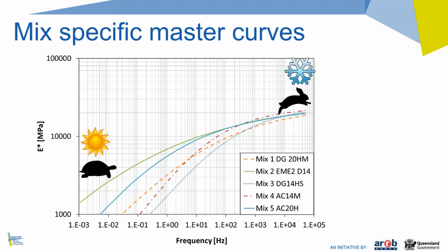No. Well, the answer is actually that it does asymptote on both sides. The sigmoidal model is actually a symmetric model. That means the asymptote that's on one side is also on the other side. The thing the slide doesn't show is that the current Austroads method, and also the current TMR supplement, limits the master curve at 1000 MPa. So that is what I did here as well.